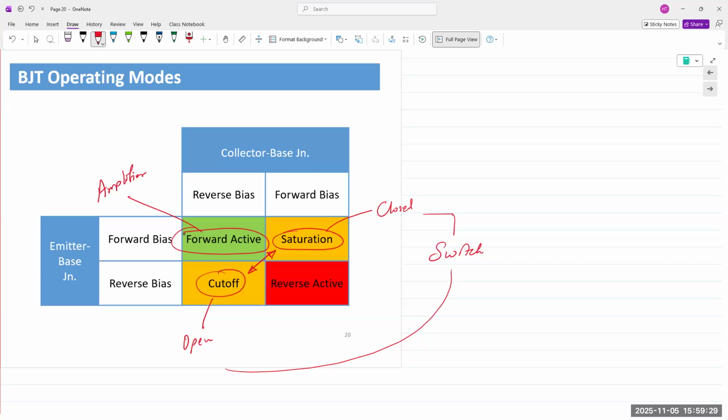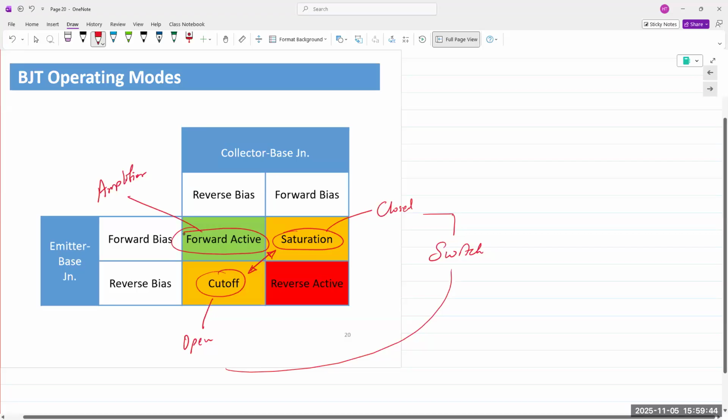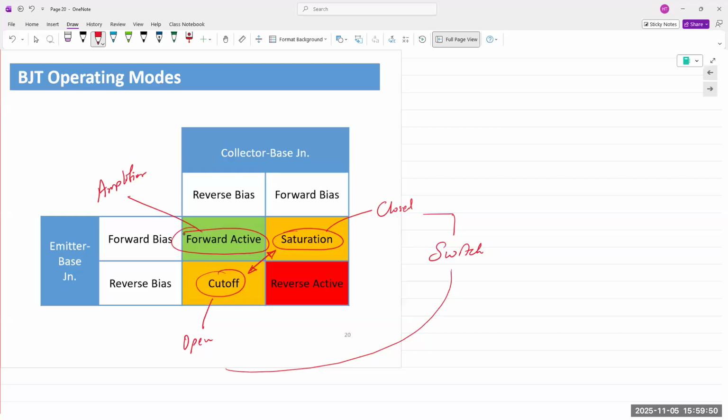If you know the terminals of your transistor and you just hook up the circuit correctly, then it's fine. But it's still worthwhile knowing what would cause a reverse active mode. If your emitter-base junction is reverse biased, nothing's happening. Electrons are not going anywhere. The collector-base junction is forward biased. Maybe some current flows through that forward biased junction. Other than that, nothing is happening. There's no amplification.